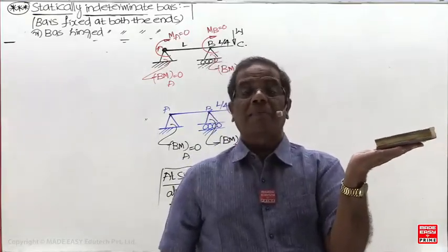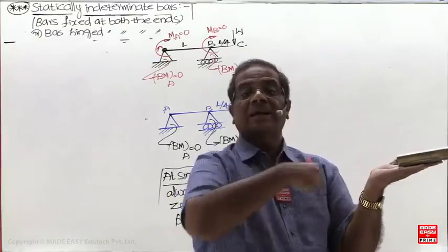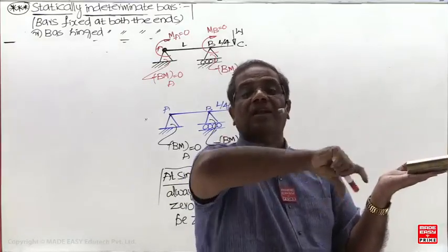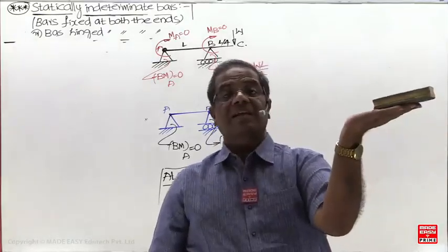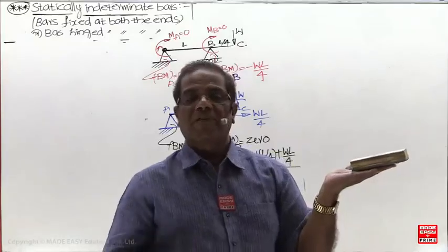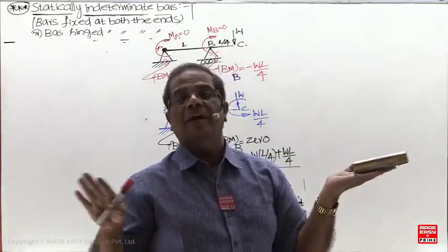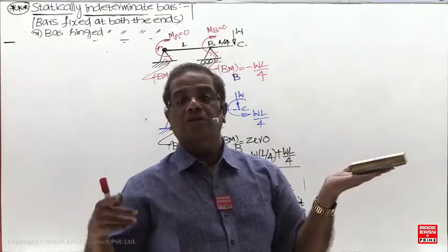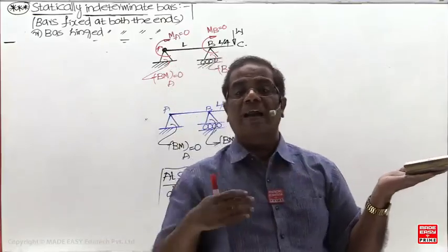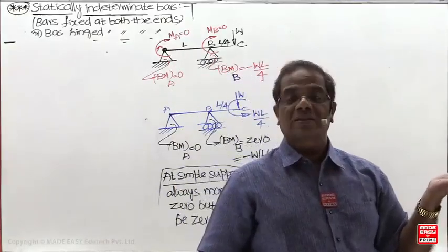So my hand is permitting how many motions? Axial motion of the duster as well as the rotation. So this hand is taken as a roller support. Whenever an axial motion is permitted for a horizontal member, we directly call it a roller support.